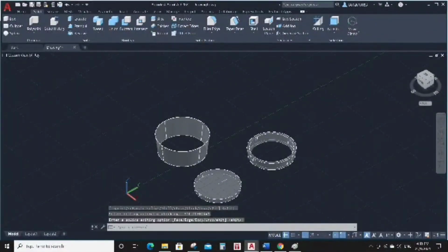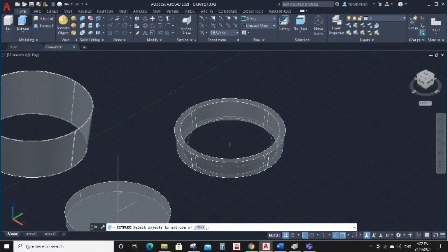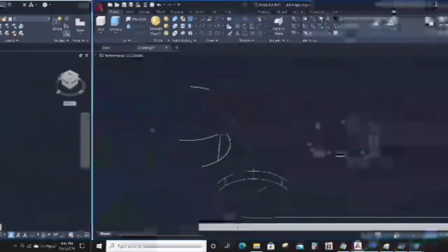After that, go to the top section and do the same step, but the offset distance is 2 mm. To make the plate part in the middle section, firstly make a line at the height of 15 mm at the center mark of the circle. Then I select the circle and use extrude to make a 3D object. The object will become like this.